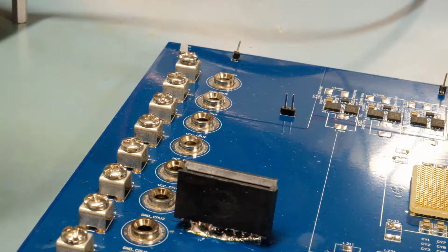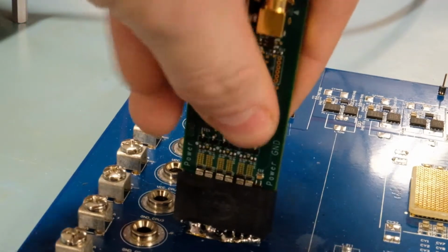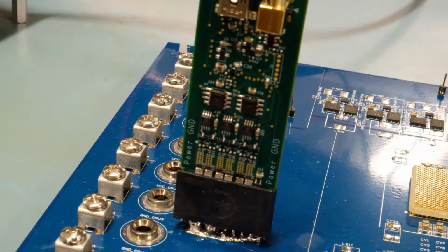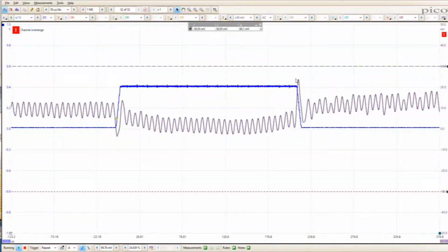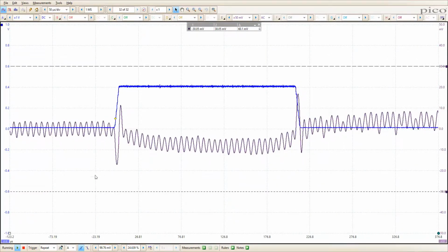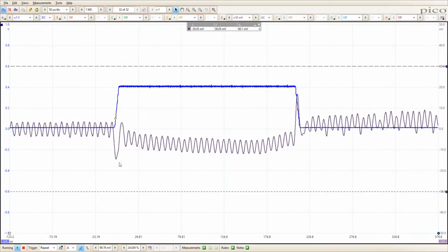Next, test the converter with the Loadslammer to see how it reacts. Measure worst case at the critical load, as this testing includes PCB trace resistance. If there is margin before exceeding regulation limits, then your circuit is a candidate for reduced capacitance.